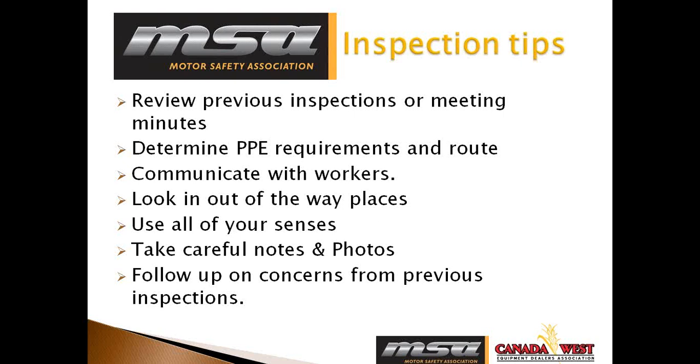And to use all your senses. Don't just go by what you're seeing. Smell. You may be able to smell. Is there a vapor or paint fumes? Is there noise, excessive noise levels? So those are things to be aware of when you're doing the inspection, to use all of your senses. I'd probably not recommend the taste, though. You may not want to taste certain things when you're doing an inspection.